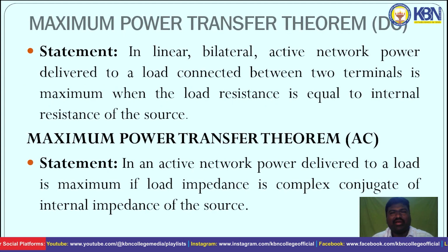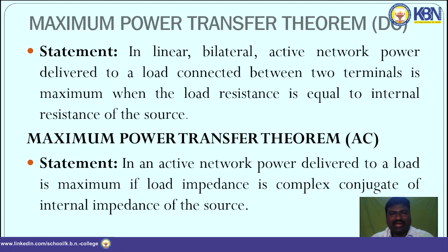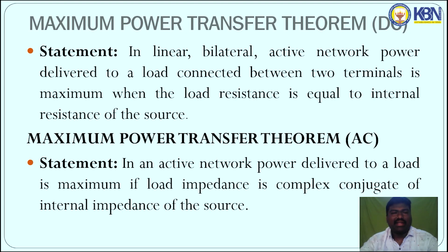Maximum power transfer theorem in DC source. In a linear bilateral active network, power delivered to the load connected between the two terminals is maximum when the load resistance is equal to the internal resistance of the source. That means RTH equal to RL.